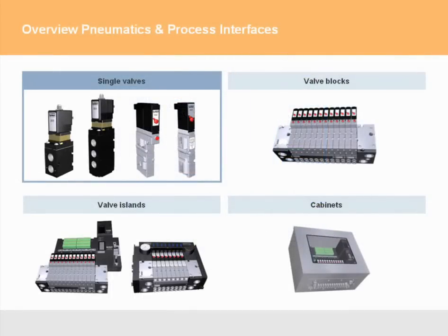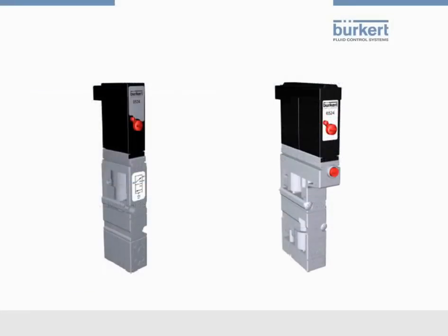Besides the Namur valves for direct mounting on the actuator, there are other pneumatic valves which are, due to their compact design, mainly mounted on valve blocks and valve islands. Types 6524 and 6525 belong to these kind of valves. Type 6524 as 3-2-way or double 3-2-way version, together with Type 6525 as 5-2-way version, is based on a flipper